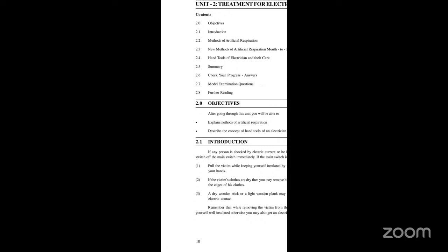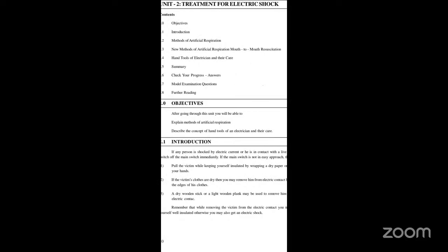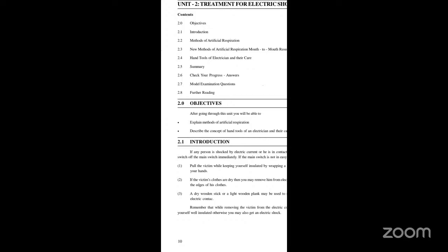Remember that while removing the victim from the electric contact, you must keep yourself well insulated, otherwise you may also get an electric shock. If we remove one person, we may also get shocked. So we must take some precautions.